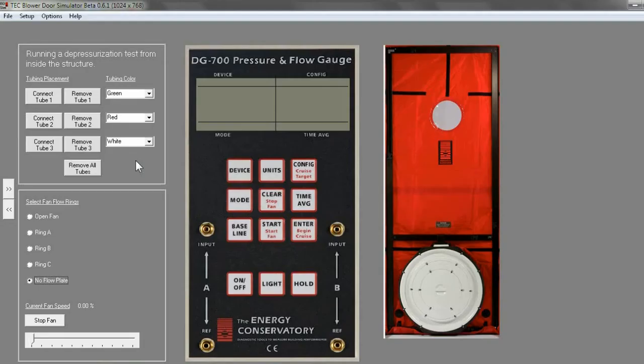In this section, we'll be demonstrating the blower door simulator, and this allows you to do a virtual blower door test that includes some baseline readings that include stack effect and the wind effect of the building. And it will also introduce a way to determine the accuracy of your test on a windy day and making density corrections, so you'll be getting more accurate blower door readings.